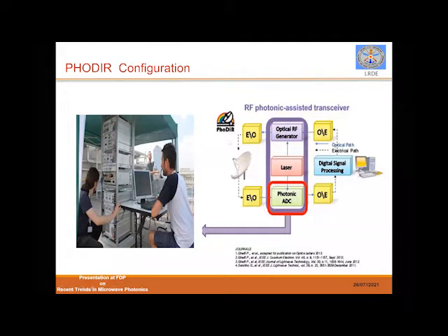So in this radar system, what I could gather was that whatever comes from the antenna output is converted to the digital domain and given to the signal processor. Similarly, in the transmit path, the baseband signal is given to a photonic RF generator, and the output is converted back to the RF domain before giving it to the antenna. So just imagine a simple rack with an antenna as the total radar system.